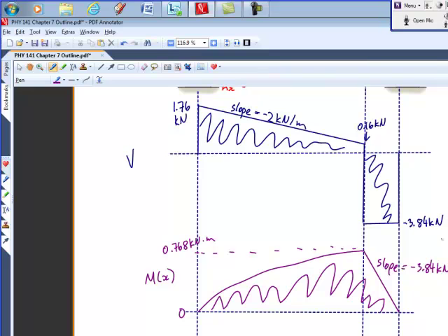Yeah, okay. So if it's just a cantilevered beam, then it's going to cause it to go more concave on the bottom, or convex on the top. That's why when we looked at the cantilevered beam, we had a negative bending moment everywhere. It started at 0 at the free end, and then it increased to the maximum negative value here. Okay.